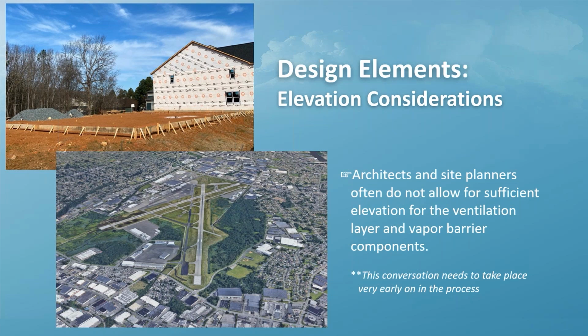This was really tricky because this site historically was manufacturing buildings and a lot of things that have to do with fuels from the airport. So there was high groundwater, silty soils, and a cocktail of chlorinated solvents and fuels. And the goal was to go passive. And these soil gas concentrations in the predecessor buildings were in the neighborhood of 1 million micrograms. But what we did is we were able to figure out the correct stone bed height, the pipe diameters, the conveyance, get everything worked out, and work with the elevation.